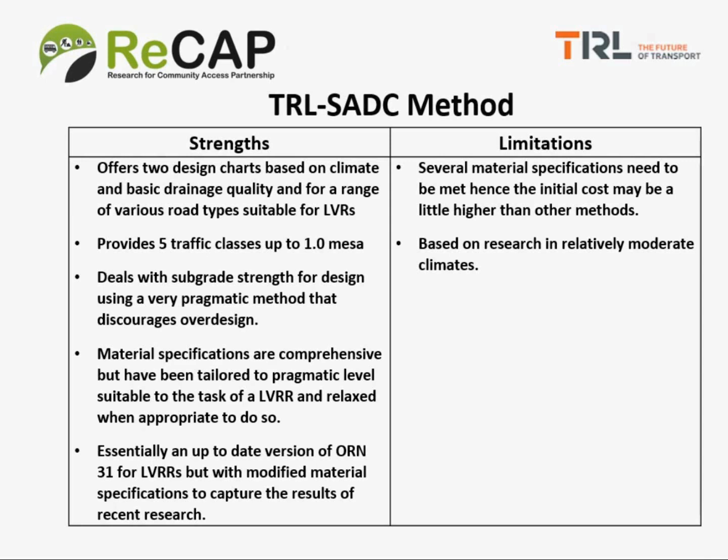The material specifications are comprehensive, but again, they've been tailored to a pragmatic level suitable to the task of a low volume road. In other words, they're not as conservative as the Overseas Road Note 31 material specifications. In fact, I suppose the best description of the TRL-SADC method is it's essentially very similar to Overseas Road Note 31 in form, but modified. The materials specifications are modified to capture the results of recent research.